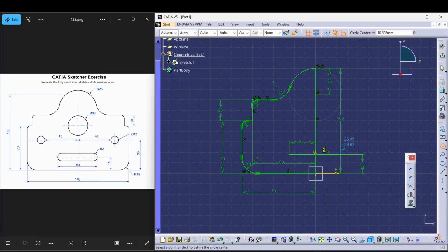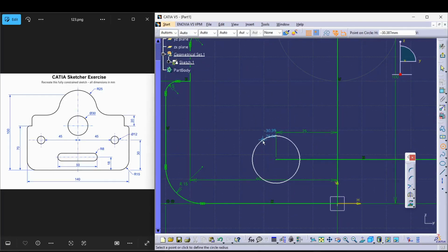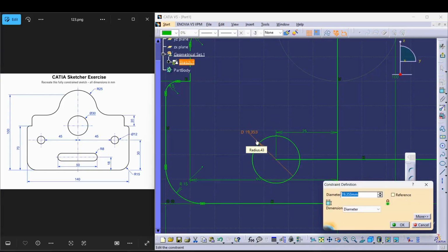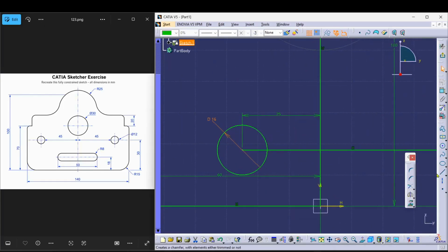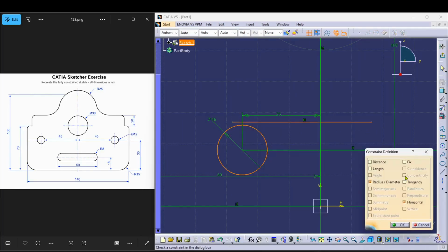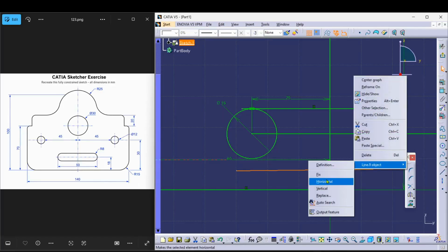Here we are doing nothing but creating a reference to place our slot as per dimension. For any sketch, it is one of the key requirements to have references given correctly. Now we will place the circle with the given diameter as per the input. Then we will add lines on top to complete the slot, making sure the lines are tangent to the circle. This will create our slot. However, we will keep one side of the sketch open as we need to perform a mirror operation after completing the first side.